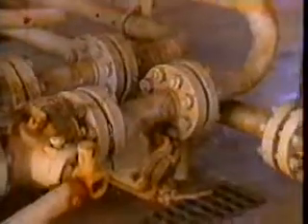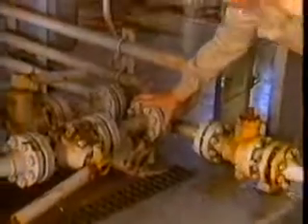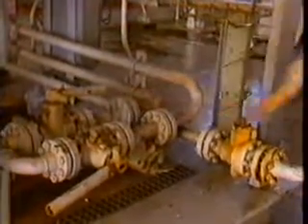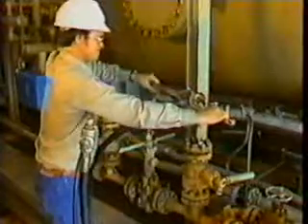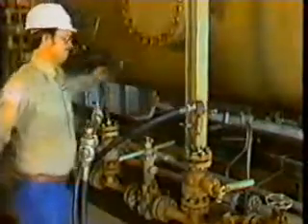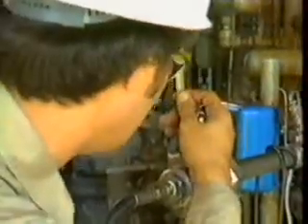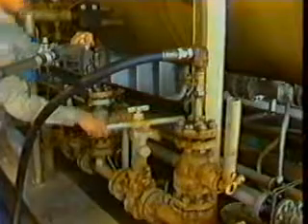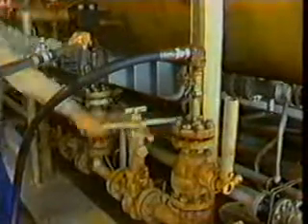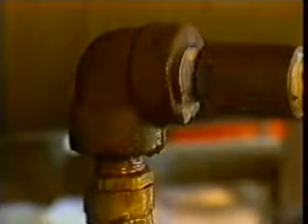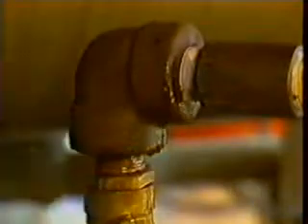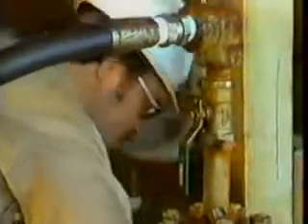To prove a meter using a master meter, you need to make sure there is a working strainer upstream of the master meter, and then connect the master meter. Record the operating flow rate, temperature, and pressure of the flow meter. Now direct the flow of the meter being proved into the master meter. As in proving with a bidirectional pipe prover, check all valves to be sure none of the flow through the meter is bypassing the master meter, or that the flow through the master meter is bypassing the meter being proved.